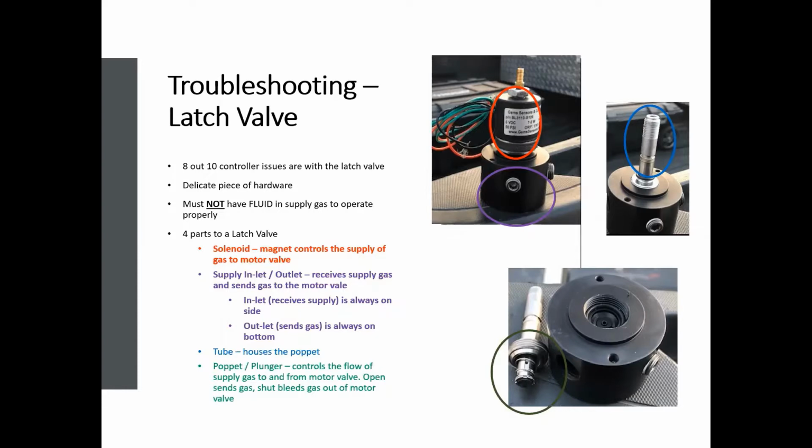You should hear the solenoid clicking. If it's clicking and you're not seeing the valve open or close, you want to make sure you don't have a plug in your line somewhere, because that means you're probably not getting gas supply to send to your motor valve.